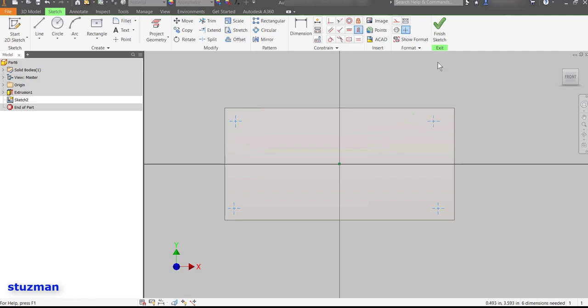Now let's tell it to be vertical. I want that one to be vertical with this one. I want this one to be vertical with that one. So now they're locked together horizontally and vertically. Now if I move, you can see that these two are moving, but it'd be nice if, when I move it, it would be symmetric across the x-axis, which is just down here, and also symmetric with the y-axis as far as these moving with it.